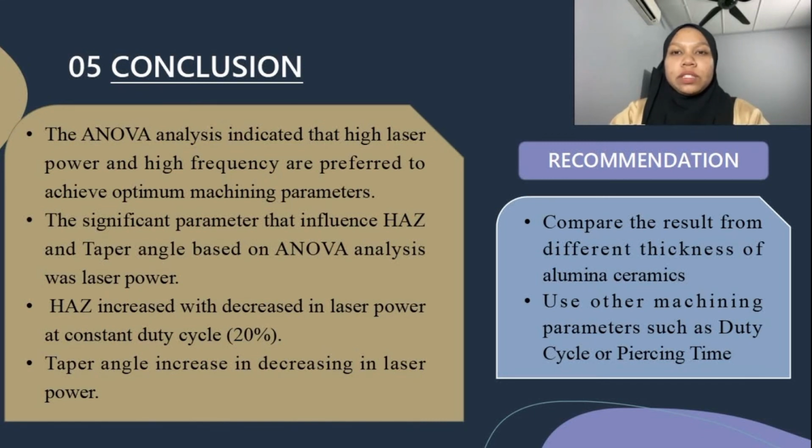The recommendations for future works to be implemented are: compare the result from different thicknesses of alumina ceramics. Next, use other machining parameters such as duty cycle or pressing time.